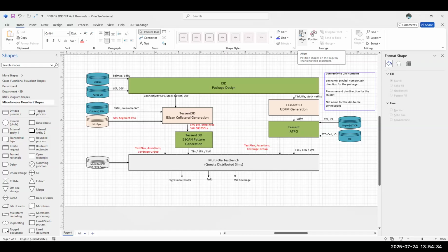But it's already set up to do... I'm going to use the word packaging, but what I mean is a software package, like a collateral package for a product, not a package for a chip, right? It's the right IP exact that deals with the collateral packaging, telling you where the GDS files, Liberty files, constraints, things like that are, right? We don't want to replicate that unless we have to.